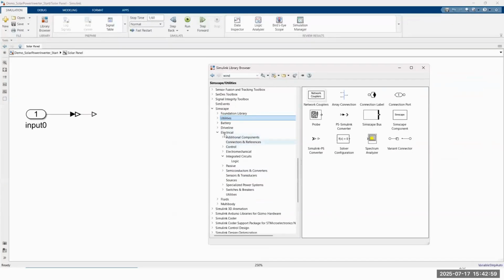If you can see here, there are a lot of electrical systems libraries available for you. There are already ready-made control systems that you can use, and then parameterize, and later on parameter estimate or tune so that it meets your requirements. It also works with electromechanical, with motors, PMSM, reluctance, stepper motors or synchronous motors.